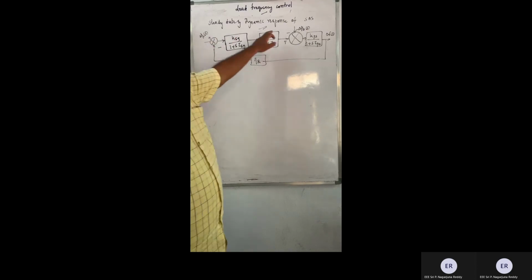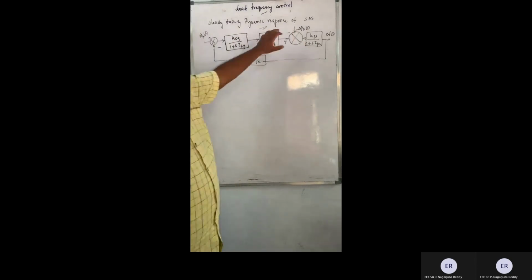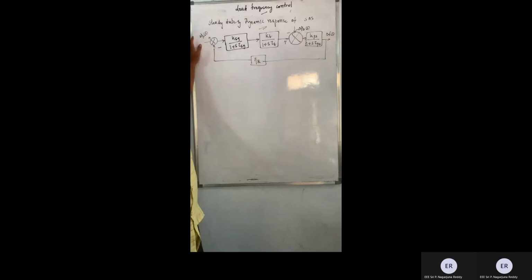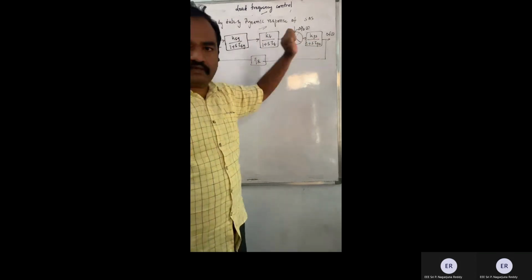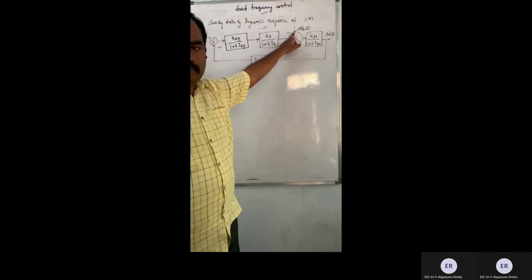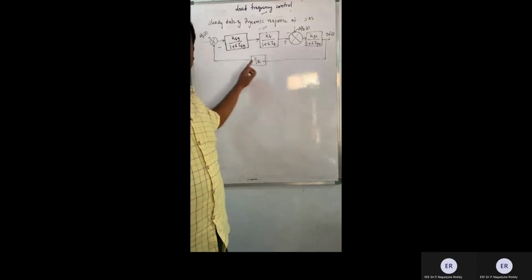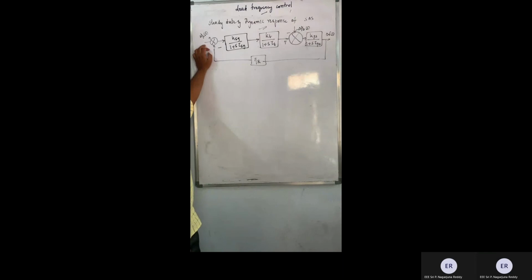Right. This is the complete block diagram of the isolated power system, or what we call a single area system, isn't it? Now, this is your manual control. This is an automatic setting, right? Because of changes in demand or your manual speed changer setting, there will be a change in frequency. Normally, the demand will be varying, so frequency will be varying. This will be countered by your manual change. But I may not need this manual speed changer setting now, so I'm going to remove it.